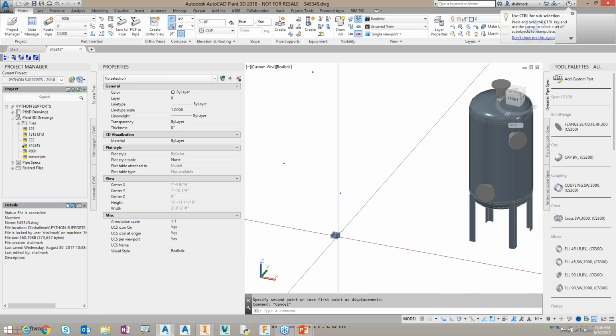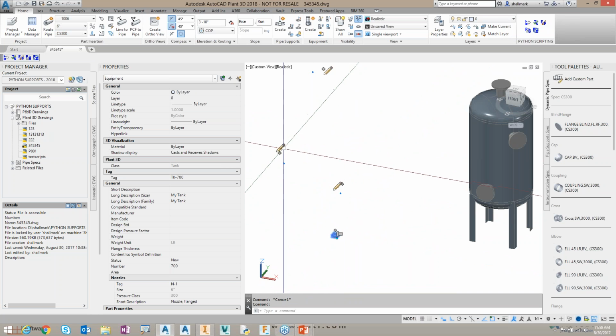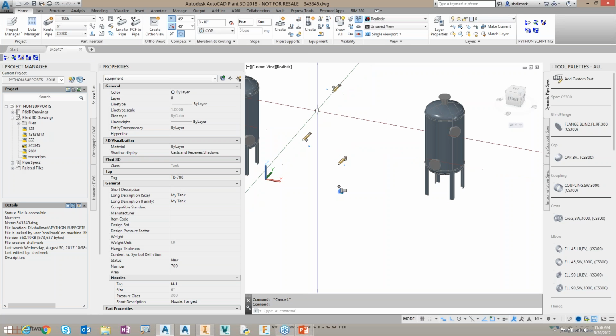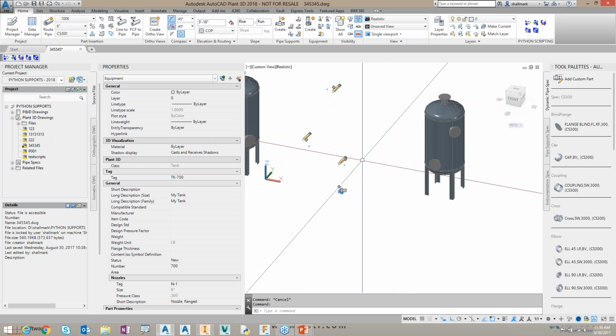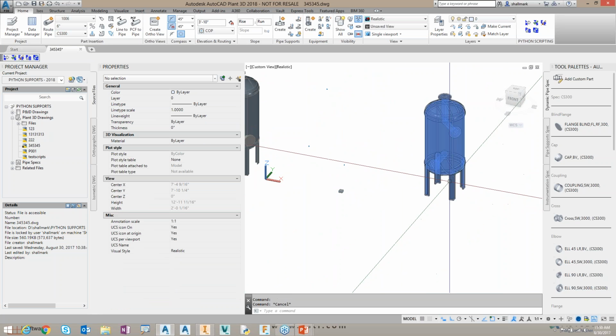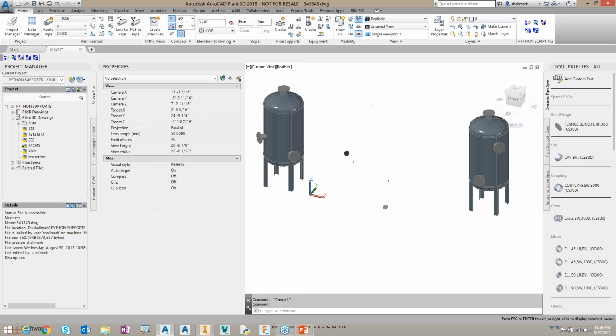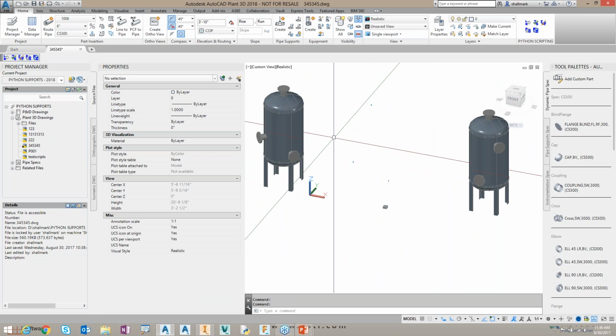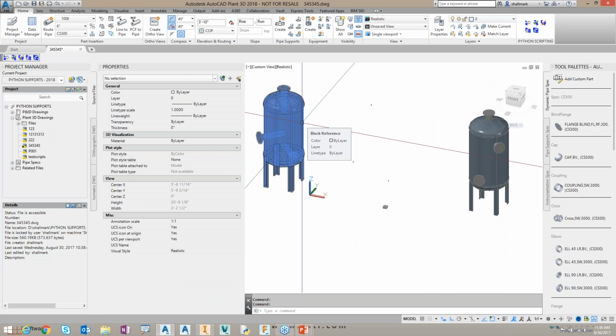But the box still remains, and you can see the box still has nozzle locations. That's very important because I want to be able to just modify the locations for these rather than have to recreate them all. It's going to be a lot easier. Now, this tank is only 3 nozzles, but what if you had one with 20, 30 nozzles on it, but only 3 nozzles changed?